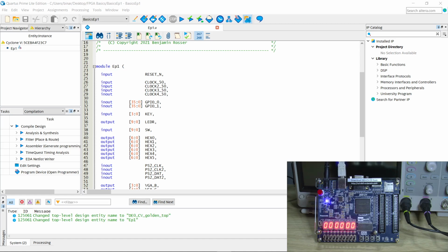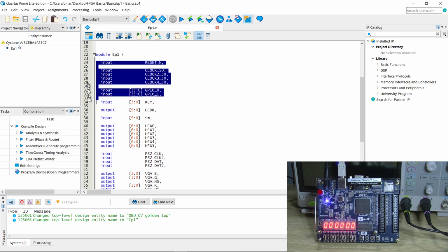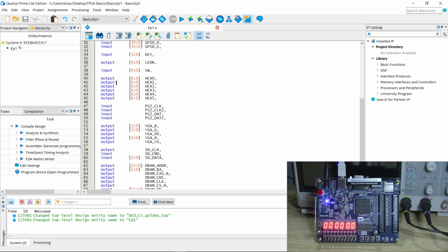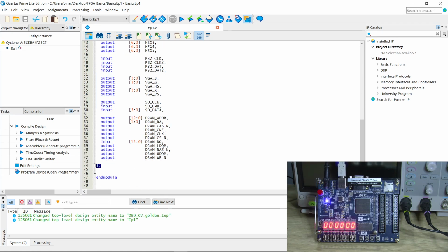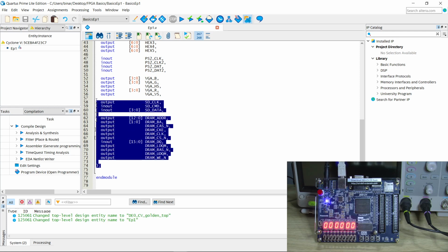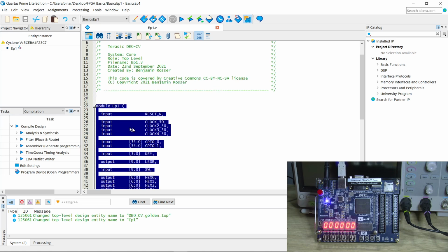So in Verilog HDL, we make use of a bunch of different modules. If you've done C++ programming or another object-oriented programming, you can almost think of a module like an object that contains a specific set of functionality, that can contain other modules inside it, and those can be connected in different ways and wired up in such a way to get a more complex device. The first part of the module, in between our parentheses, is a bunch of inputs and outputs. So down to here is basically describing all of the I/O for our module, that whole section there.